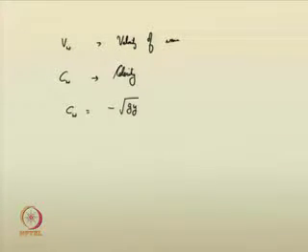I have Cw equal to minus root g y, and also Vw is equal to V bar plus Cw. This you are quite aware of: the velocity of wave at any section is equal to the velocity of water there plus celerity.